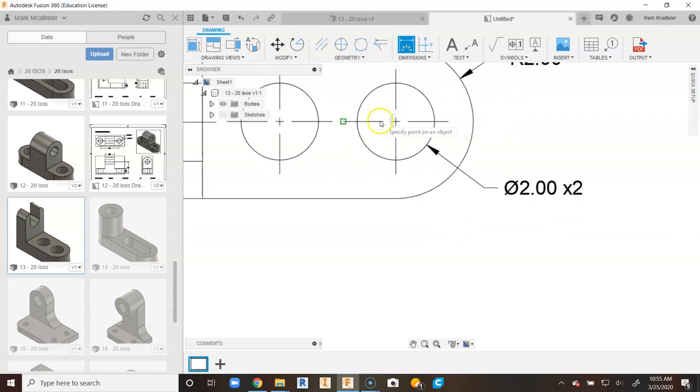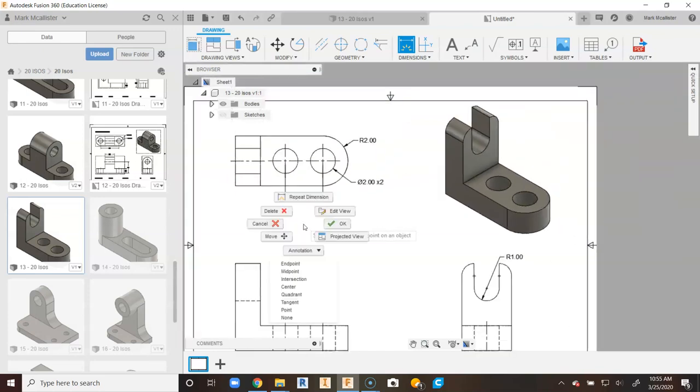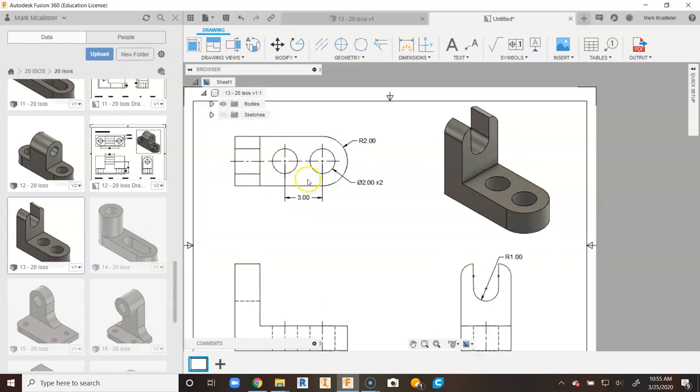That point right there from here to here should be a solid number of 3, and I'm going to go ahead and drag that down in my top view. Now you might think, why are you making this in the top view? Because I'm trying not to drag up too high outside of a view. I think it can make it a little bit easier to see the closer that you are to the actual feature. So here in the top view, let's come up here and let's say from our, I have to go to dimension, I went to center line.